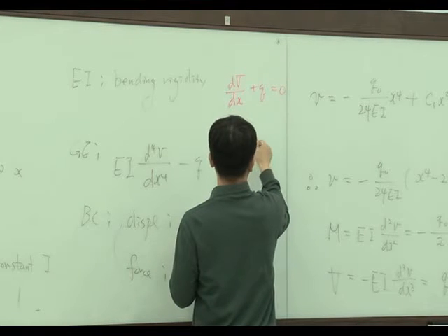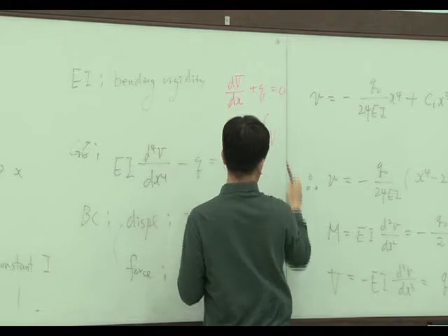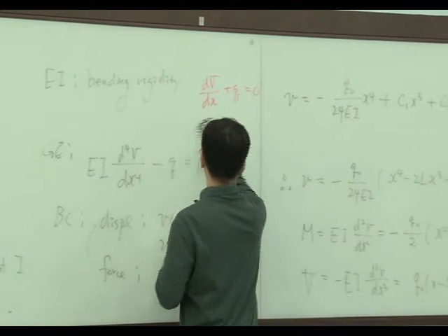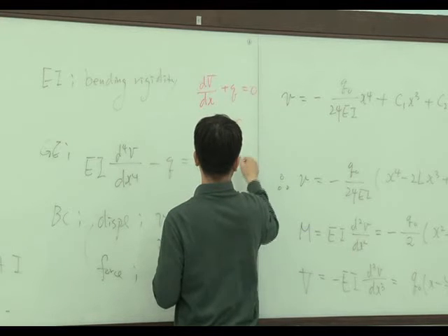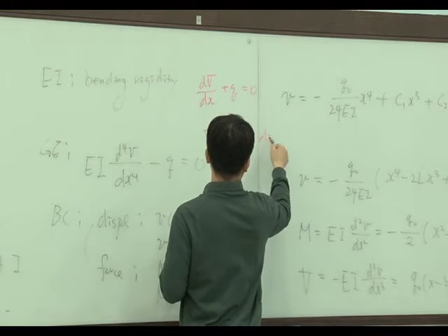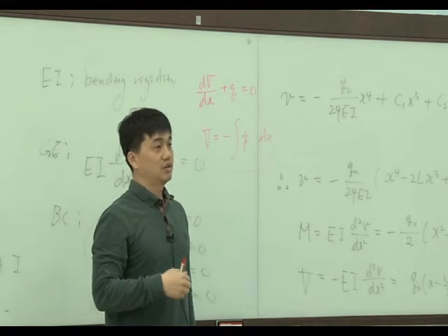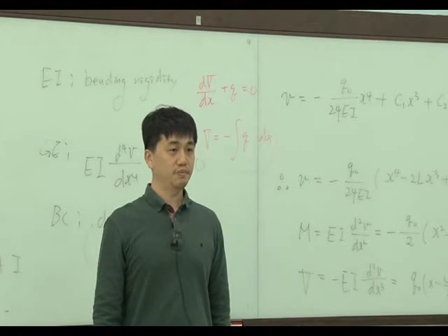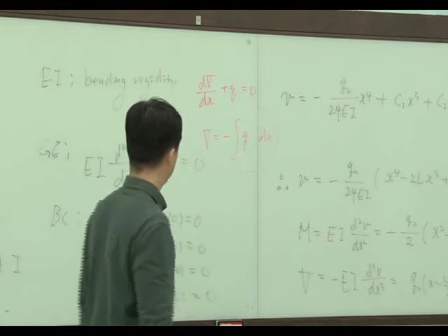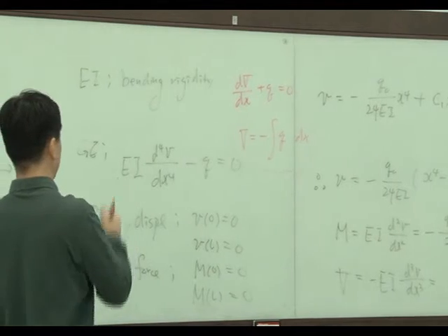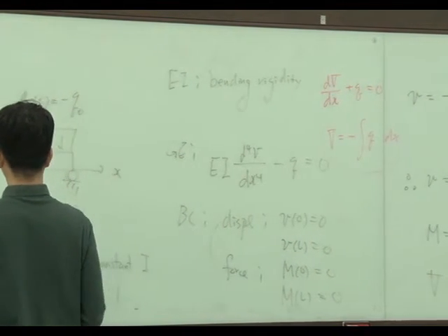So q equals minus dV/dx, and V equals minus the integral of q dx. So we can calculate the shear force diagram from the distributed load.